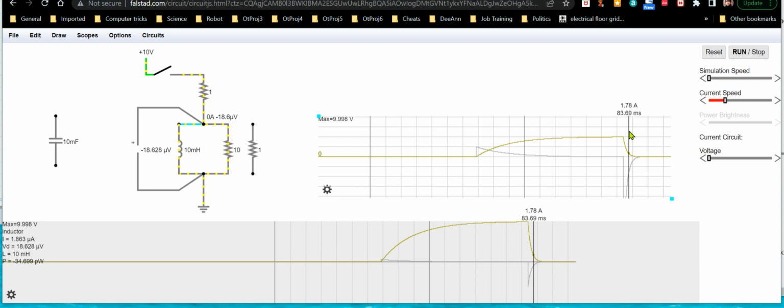But because it's generating 100 volts, it will dissipate, it will get rid of that energy really quick. And that's what happens, so this resistor basically is absorbing all that energy, but because it's 10 times as large, it absorbs energy at 10 times that rate. It's got 100 volts across it and 10 amps going through it. But since it's 10 ohms instead of 1 ohm, it's able to eat that energy up 10 times as fast. So basically, that's what happens here.